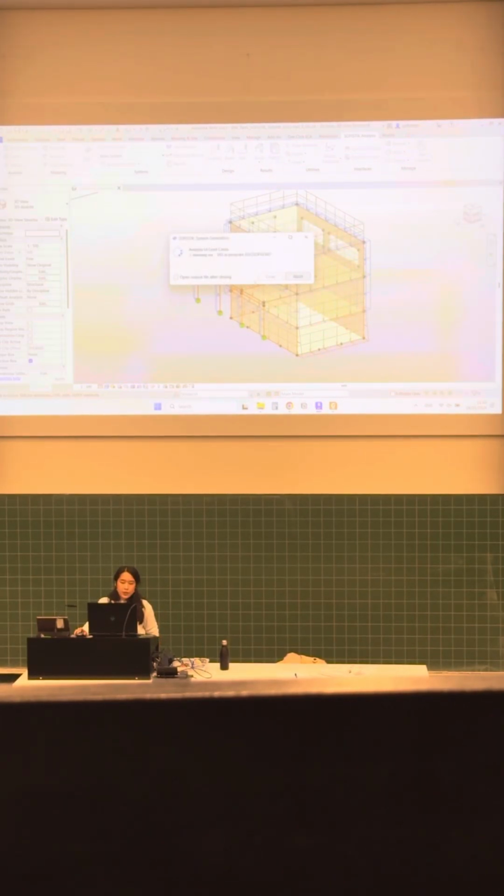for the system generation. This basically generates the FEM model, which we will then look at in a different environment. And okay, we see that it gives me, and probably you, warning number 185. To see it right now, what we can do is tick it and close it.